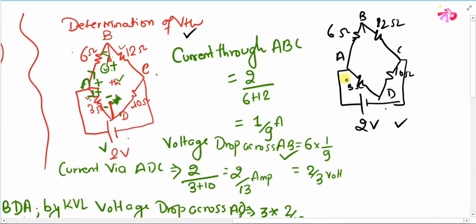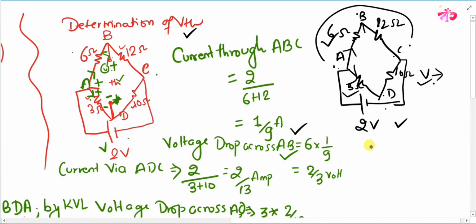After drawing the circuit, you can easily notice that points A, B and C are in parallel. This is in parallel with ADC, and similarly in parallel with AC. From that, we can easily find that voltage in parallel is the same. That's why we identify the current across each branch. After identifying the current, you can easily identify the voltage drop of each resistor. So we identify the voltage drop of AB. In a similar manner, you identify the value of DA.